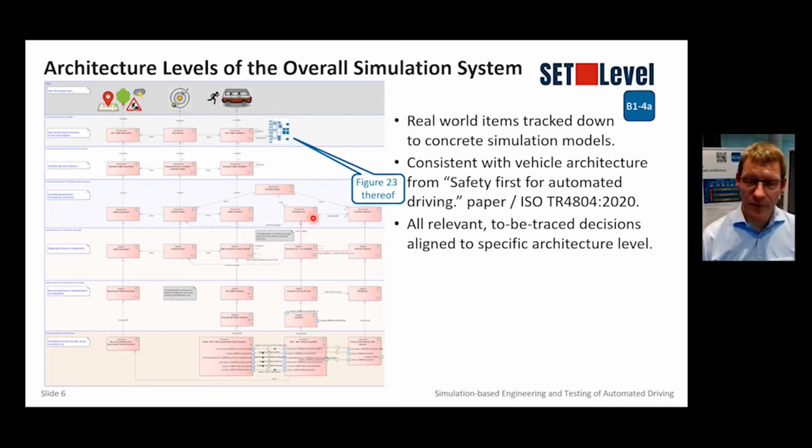And then the next level would be a logical level, which could also be subdivided, with an upper logical level where we say, okay, for this and that function, what components do I need? Frequently, for one function, you need to have several components, like, let's say, an anti-blocking system. You have to have the control system. You have to have the brake actuators, etc. You have to have the sensors, and all together are necessary for one function. And vice versa, sometimes several functions can be implemented by one component. So these are really important decisions, and mistakes can become dangerous or expensive.